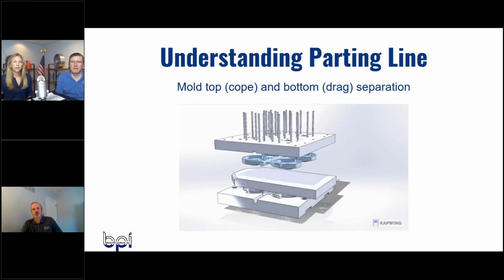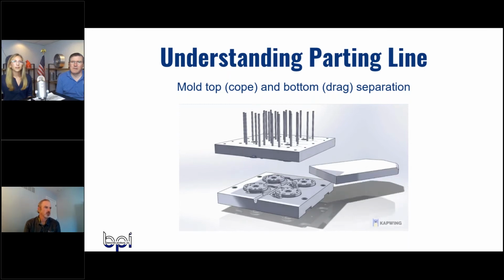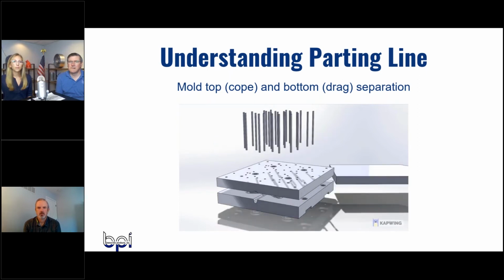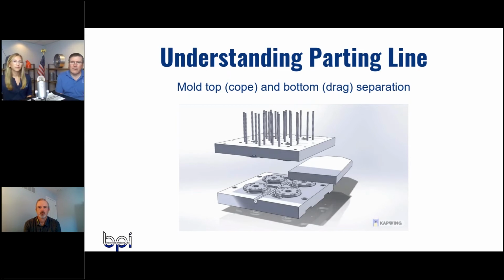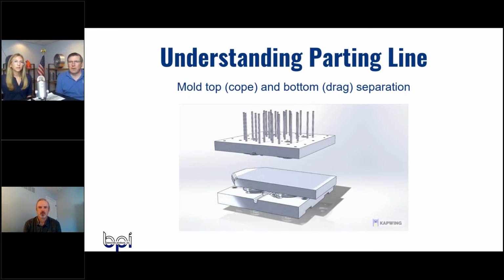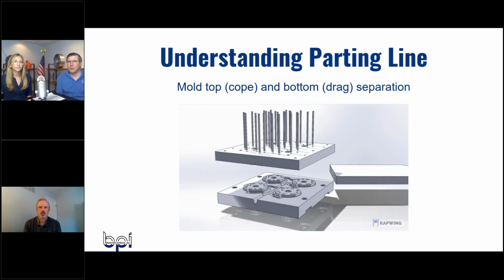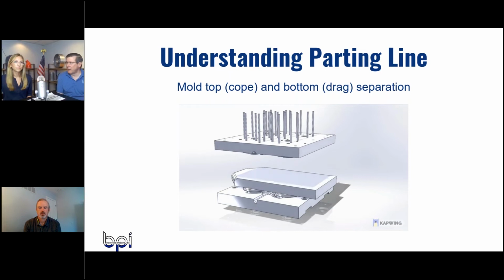Awesome. So just for you guys to quickly understand what you're looking at, we're showing what a parting line, so the cope and drag, look like for a mold. That's why you have two separate halves and you require draft, right? Right, and we talked about the draft, and that's part of what's going on there. At that parting line, you want the draft to move away from the parting line so that the parts release accurately off the mold.